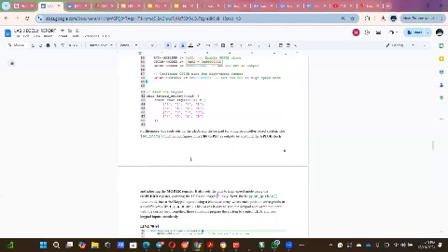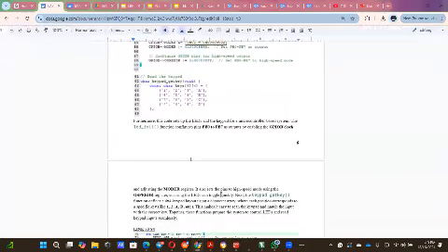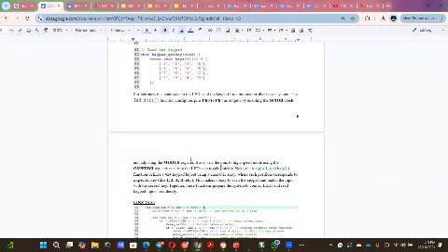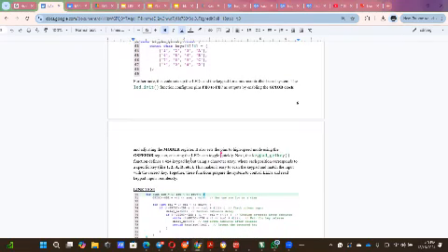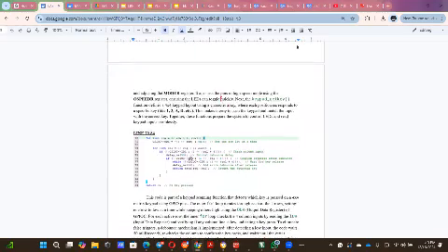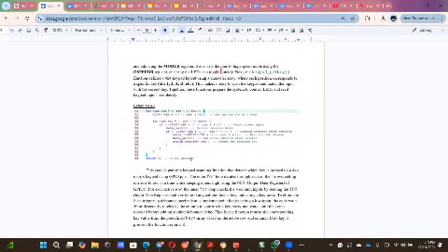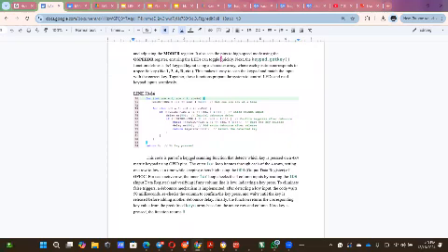Next, the keypad's get key function defines a 4 times 4 keypad layout using a character array, where each position corresponds to a specific key, like 1, 2, A, D, etc. This makes it easier to scan the keypad and match the input with the correct key. So together, these functions prepare the system to control LEDs and read keypad inputs seamlessly.